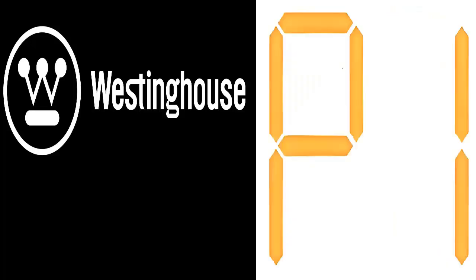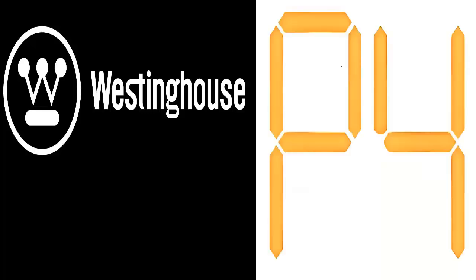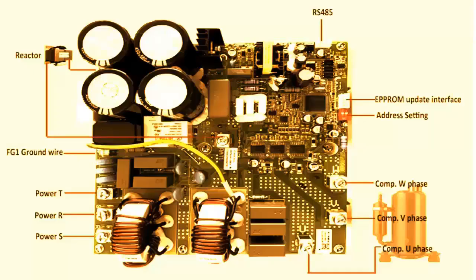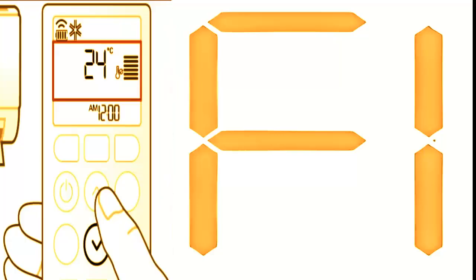In this video, we will discuss the fault and protection codes F1, F2, F3, P0, P1, P2, and P4 in Westinghouse air conditioners. Generally, error codes F1, F2, and F3 are linked to specific issues. F1, mostly related to problems with the outdoor ambient temperature sensor.